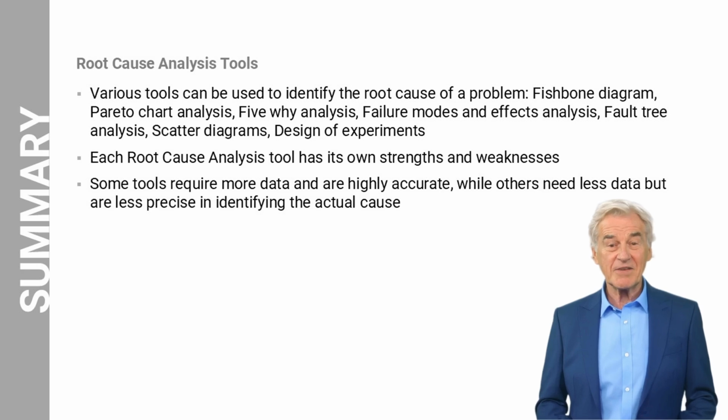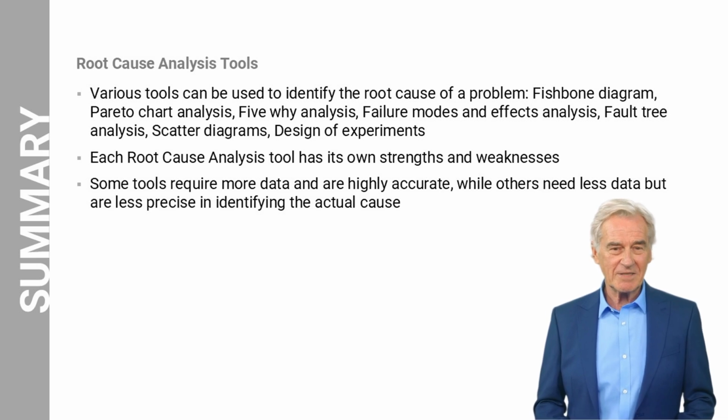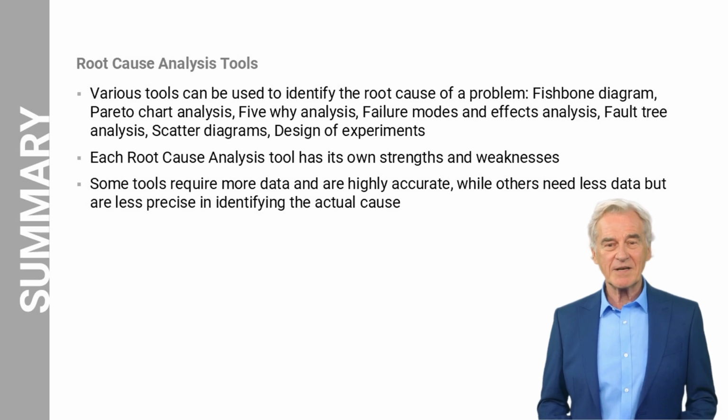In summary, various tools are available to identify the root cause of a problem, including the fishbone diagram, Pareto chart analysis, 5Y analysis, failure modes and effects analysis, fault tree analysis, scatter diagrams, and design of experiments. Each of these tools has its strengths and weaknesses. Some tools require more data and are highly accurate in pinpointing the actual cause, while others need less data but may be less precise.